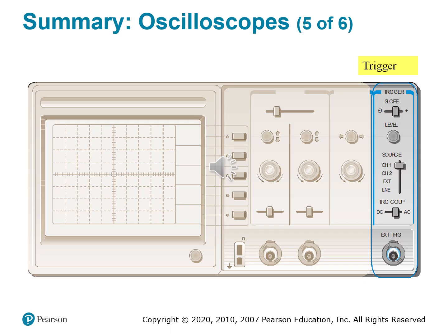What else? The trigger source: channel 1, channel 2, or some external line. This tells the oscilloscope which signal to watch for the trigger. Channel 1 and channel 2 use the waveform from one of the input channels. The EXT, or external, is used as an external signal as a timing reference. And then line syncs to the AC mains signal. So handy for power analysis.